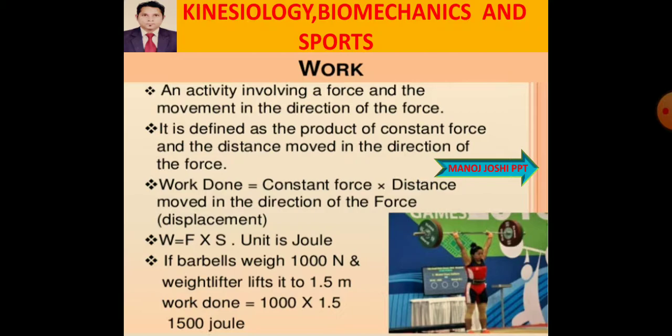A barbell weighs 1000 Newton and the weightlifter lifted it to 1.5 meter. So work done equals 1000 into 1.5, and it will be 1500 joule.